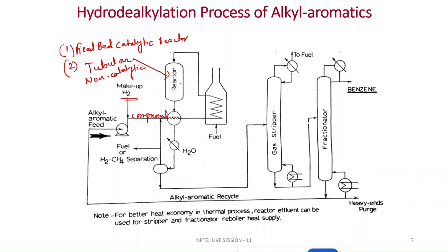after the hydrodealkylation occurs in the presence of the hydrogen, the product will be passing through the same preheater. The heat exchange will be performed, and it will be cooled down, and again cooled down by water circulation through the chamber, and then it comes to the high pressure gas liquid separator. So it is operated at a very high pressure condition. Okay, so here the liquid and the gas are separated, and from the gas section you can see that there is a hydrogen and CH4 mixture, right?